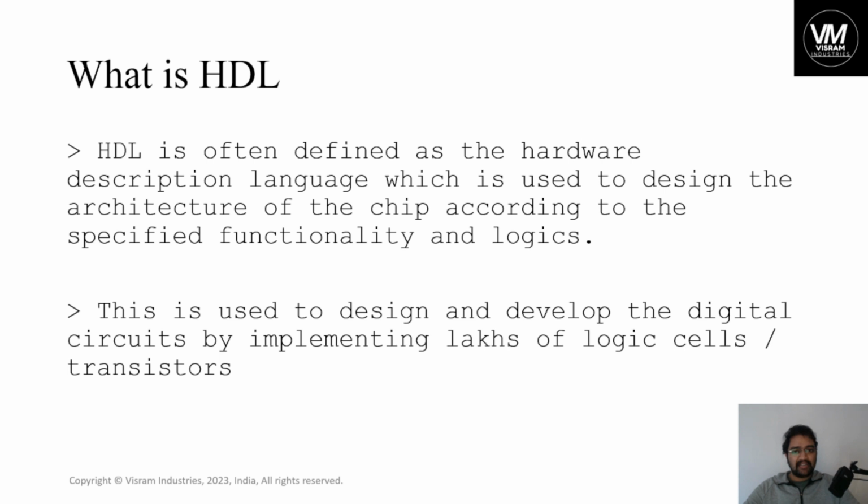All these timing paths we need to decide, and based on that, the clock frequency. The clock is the main key point in the entire chip, which decides the performance. To design the clock, we have to give the constraints at the RTL stage. Also, we verify the static timing analysis reports using different EDA tools.